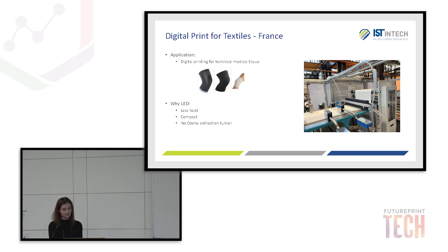So why did they choose the UV LED? In general, UV technology can be used for this sort of application. It's a quick process and the product is sensitive to heat, so things like thermal just isn't really an option. But why LED over arc lamps? Firstly, because it just worked. It's an option for the customer to look at.